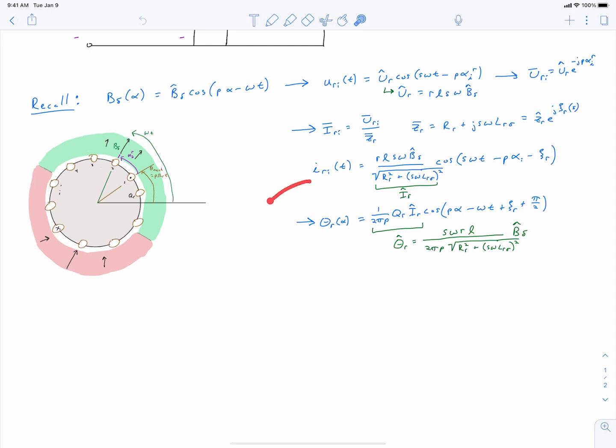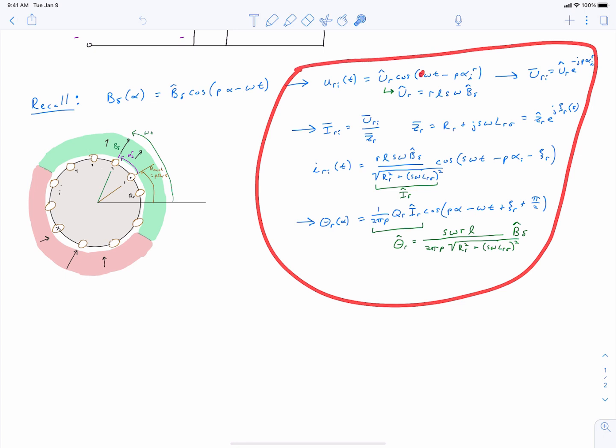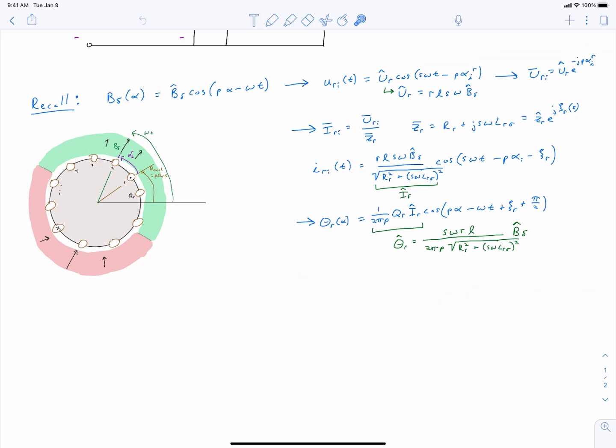And from our rotor bar current, we know what the current of all other rotor bars are, and so we can derive the total current linkage that the rotor creates, which acts on the air gap, as this expression. Or we can write it in terms of our magnetic field over here. So by assuming this quantity and a certain value of slip, all of these quantities drop out. All of these physical parameters of our rotor circuit drop out.